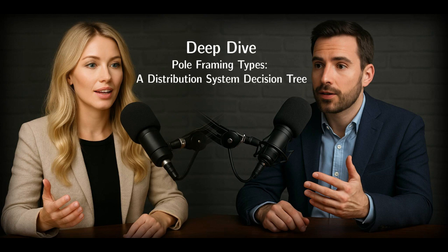Precisely. Pin or post insulators are typically for lower voltage distribution, generally. Their presence tells you that the primary load transfer is direct and vertical, mostly just supporting the conductor's weight. The rigidity of that connection means they're usually designed for through-line applications where significant unbalanced tension isn't the main worry. It's your first indicator of a relatively simple load scenario.